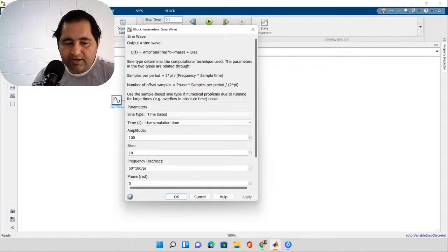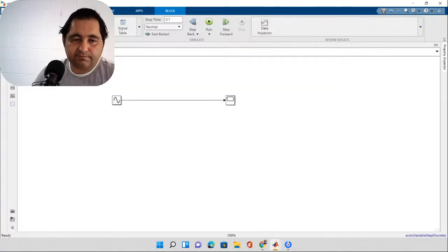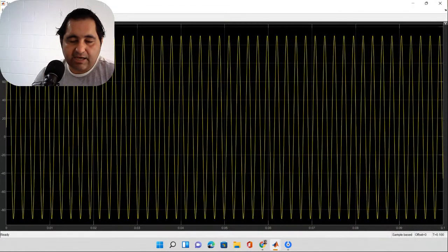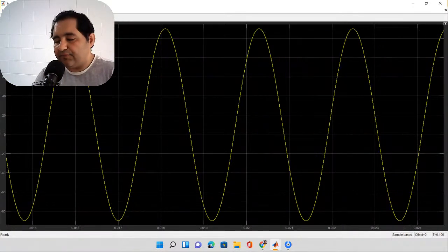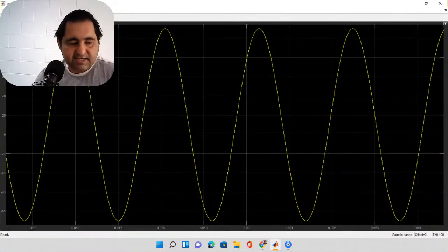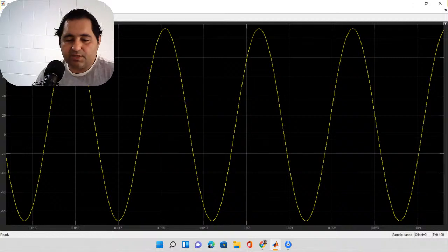You want more? 100,000 A to D. So 10 times more samples. Now the signal is a lot nicer, isn't it? Well, by the way, the reason that we were getting a sort of wrong signal was because of the frequency error that we had and the sampling errors. And now our samples are good enough and you can see a beautiful signal right here.